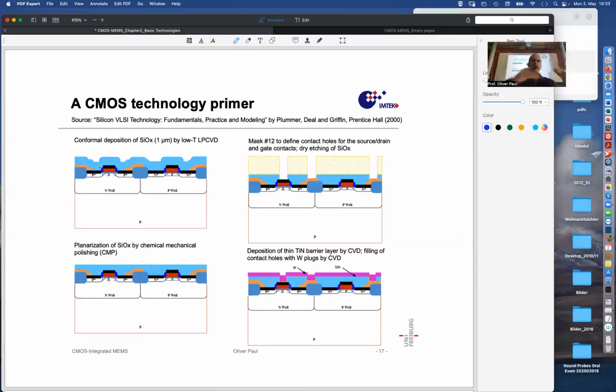At least if you have many layers of metal, and at every layer, you again have more topography building up. You may have very steep walls at some point, and you would like conducting layers to lead over that topography. The road, the long and winding road, needs to go over it, as already the Beatles sung. And the long and winding road tends to break or to be unreliable if the slope is too high.